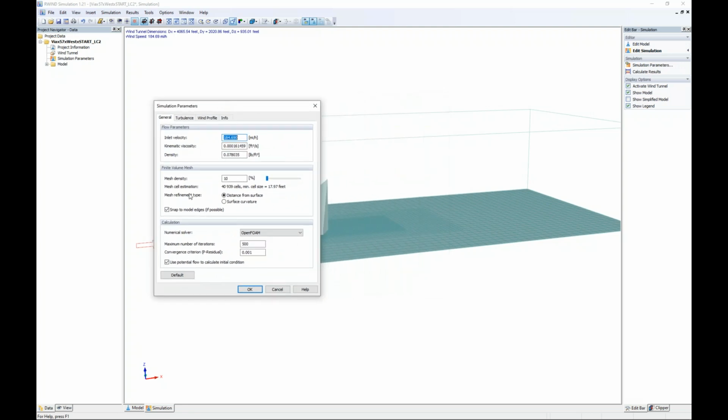We also have the finite volume mesh settings. We had set this to 10%. You'll notice that as I use this slider bar to increase this, how my mesh is changing on the right-hand side. We're increasing the number of 3D volume elements for an increased mesh total. So again, that's going to change quite significantly. So you can imagine when we're all the way at 100%, these 3D volume elements, why it takes such a significant long time to run the calculation.